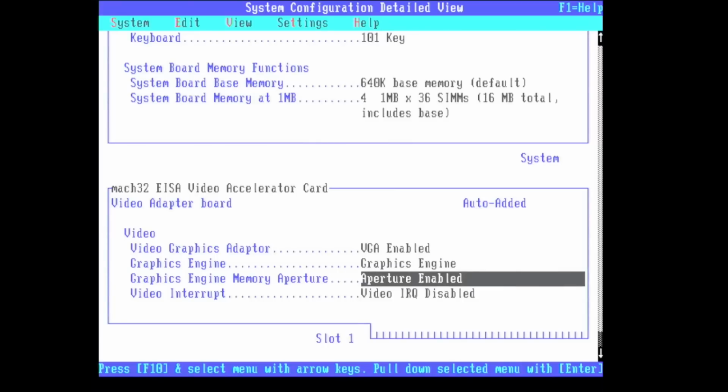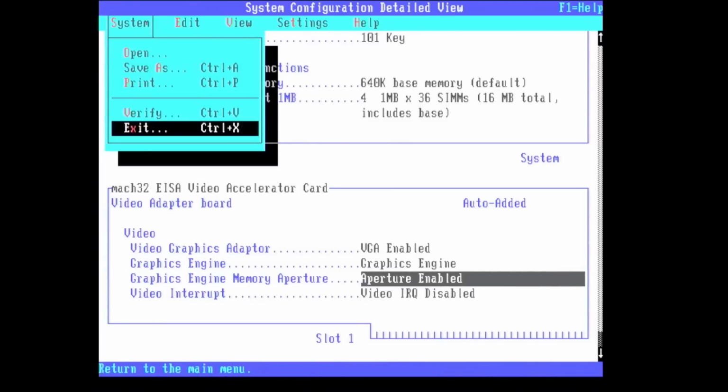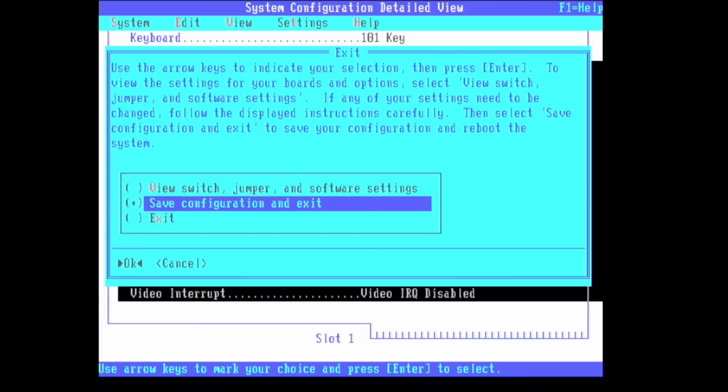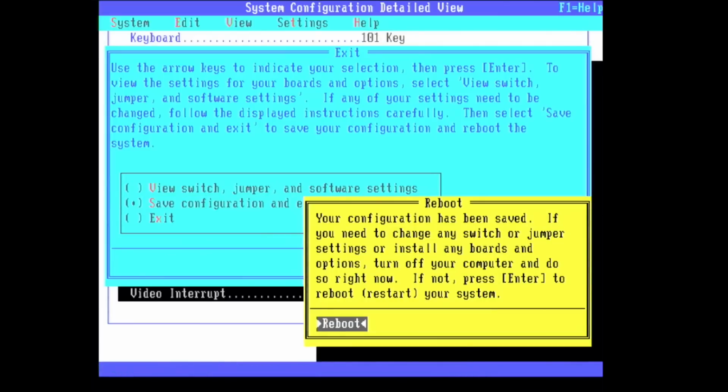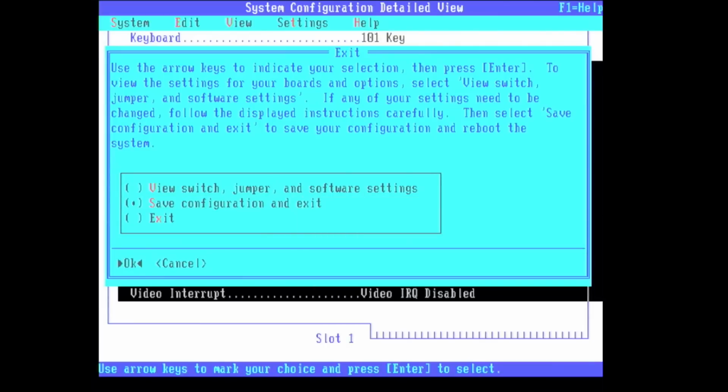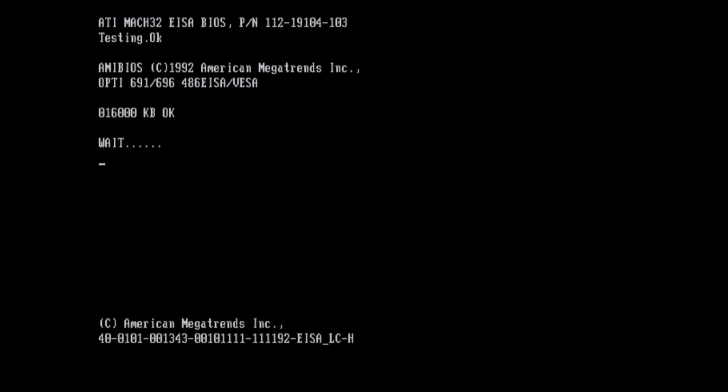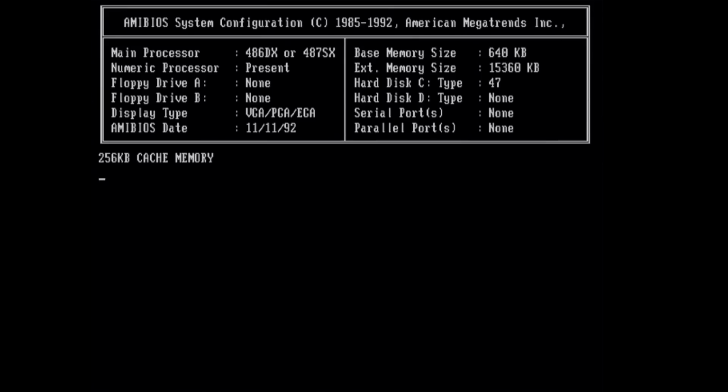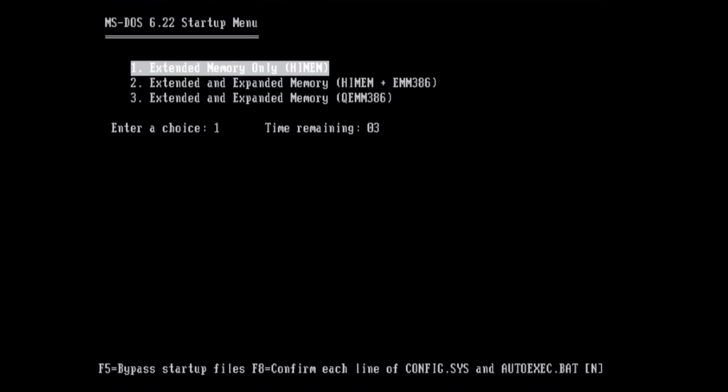So, when everything is set, the configuration can be validated and saved into the static RAM chip on the board. That SRAM chip gets powered by the external battery along with the real-time clock IC, so EISA and BIOS settings can survive a system shutdown. And after a reboot, the warning about invalid EISA configuration has gone and the system can be used like any normal ISA system of that time.